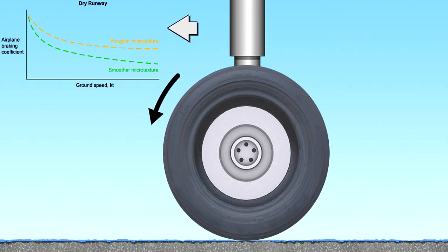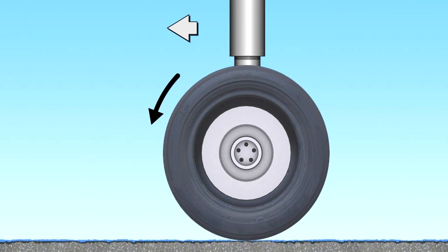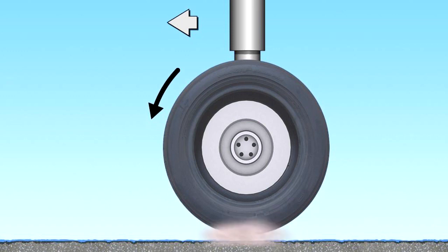Reverted rubber hydroplaning is a complex phenomenon which over the years has been the subject of a variety of explanations. Reverted rubber hydroplaning requires a prolonged, locked wheel skid, reverted rubber, and a wet runway surface. The locked wheels create enough heat to vaporize the underlying water film, forming a cushion of steam that lifts the tyre off the runway and eliminates tyre-to-surface contact.